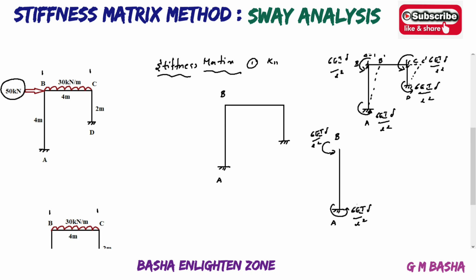So here we have to find the horizontal forces. Okay, so I will apply a horizontal force like this, that is HA. I will write 6EI delta by L square here. So I will apply the horizontal force, that is HA.